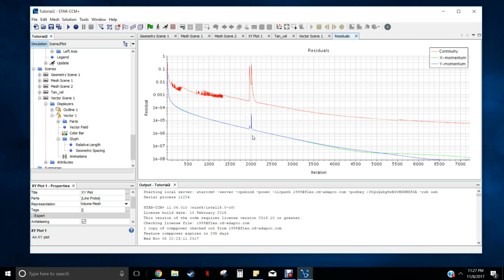I will tell you that this is not normal. I got a little impatient waiting for this to end, and was looking at some settings and accidentally changed something and had to change it back. Essentially it would normally just continue in a straight line here. If you accidentally change settings, because it is real time, these will appear, and you don't want to be changing things at this level too soon. So make sure you're not running things when you're changing things, or that'll happen. It's not super bad, but it just doesn't look great for the residuals.